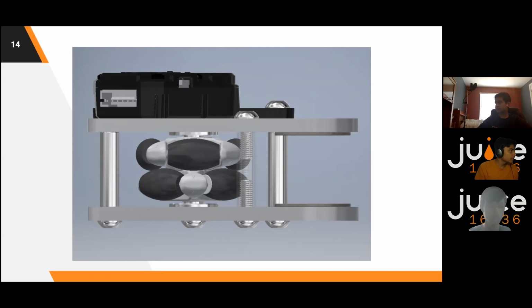Another use I've seen for 3 wheels is to have the third wheel act as a backup in case one of the other wheels fails. Yeah, so accurate rotation wasn't very important in the season, in my opinion, because in our autonomous, we only rotated once ever, and that was just to place the foundation. So that could be at any angle. So for us, having accurate rotation really wasn't that important. We didn't prioritize 3 wheels, and the Rev Hub suited us well enough for that.